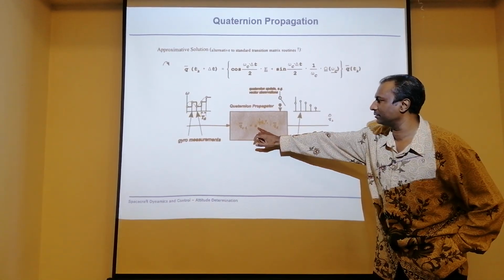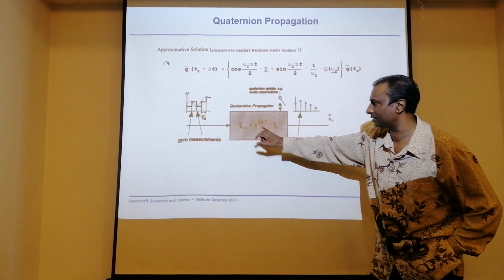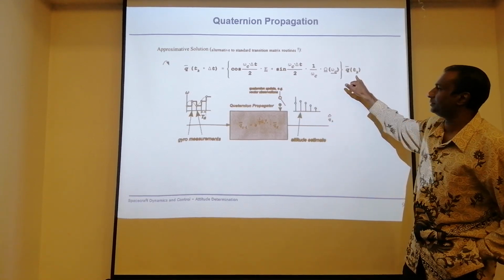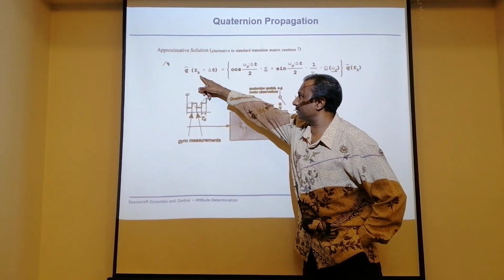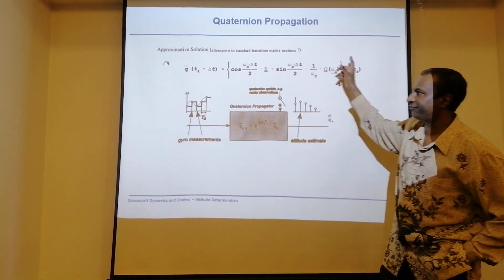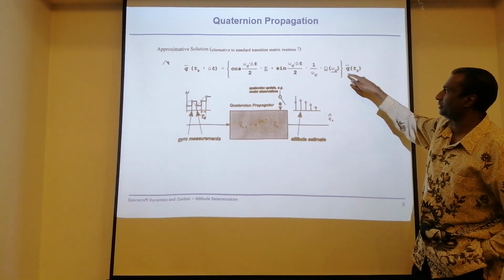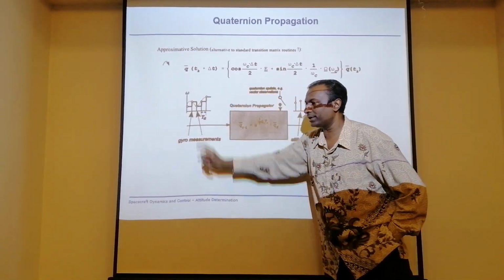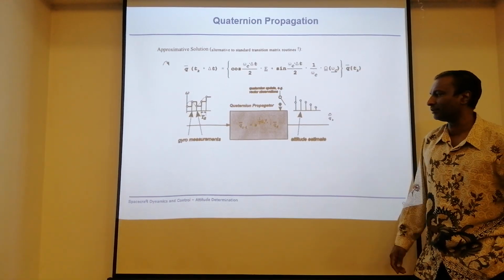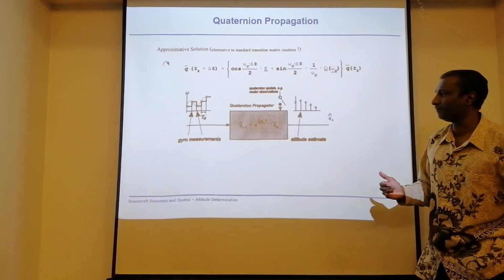But again, my quaternion propagator is defined just like in my previous slide as well. So we keep on updating the value omega in the propagator. That means this is your transition matrix. We can actually do that. And as you can see, same updates. You start with delta t, t1, update this, find the new one, then this goes back here. Okay, update, go back here, read, and then you can get your new one. So the best is that the attitude propagator is easier for you to calculate the actual deviation in attitude. Okay, go on.